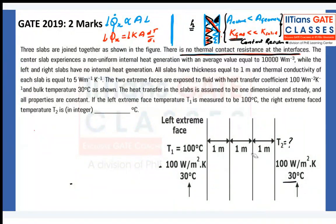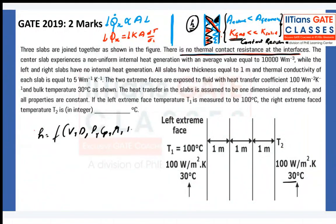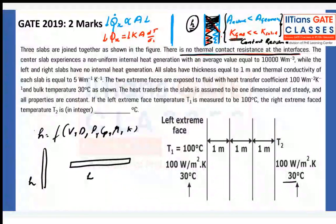Okay. Heat transfer coefficient is always defined experimentally. As soon as you change the fluid, the heat transfer coefficient will change. As soon as you change the velocity, it will change. As soon as you change the orientation of the object, for example, if an object is horizontally placed, then even if all the other parameters, velocity, rho, Cp, mu, k, are constant, the heat transfer coefficient will be different. The characteristic dimension is different, so again you cannot calculate.